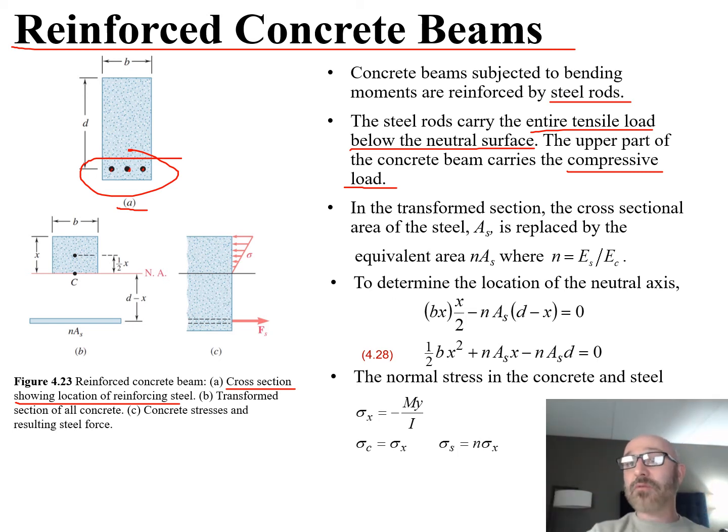So if we're going to do that for a 3-point bending like that, which you typically see on a bridge as a car drives over, it's going to bend down like that, compress the top layer, and put the bottom layer in tension. We put these rebar in strategic places right there.